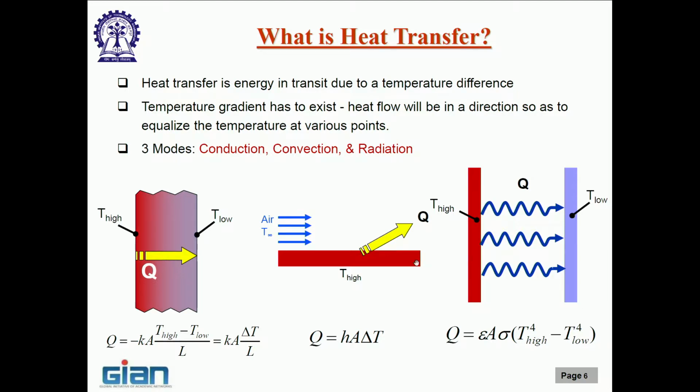So, let us keep that discussion aside for a while, and let us talk about just conduction. Conduction typically happens because when the temperature goes up, the kinetic energy of the molecules rises, and they start vibrating with higher energy, and this energy is then transferred to the next layer of molecules, and so on, and that is how the energy is transferred from one end to the other, from the hotter end to the colder end.